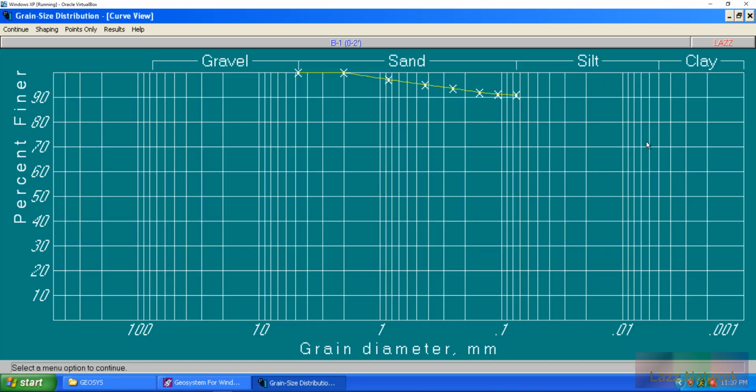So with that hydrometer portion, the way the test works is you would put a hydrometer, and that's what the device is called, in your sample and sodium hexametaphosphate solution, and then you would wait for it to stabilize, and then you would take a reading on it.